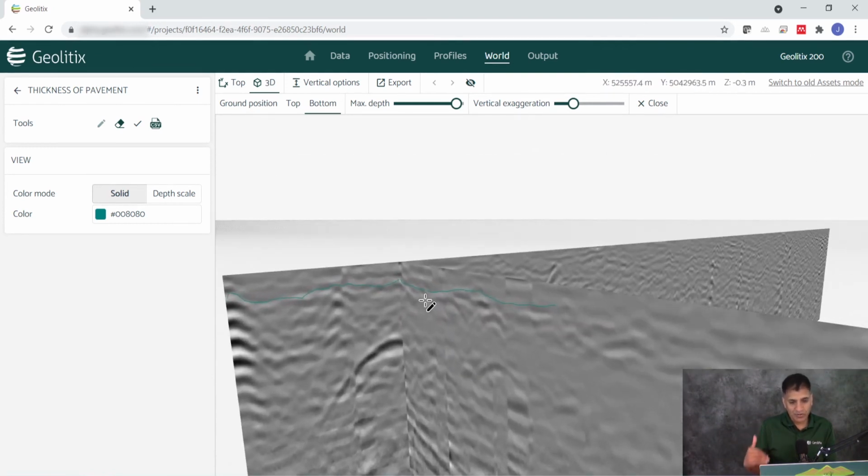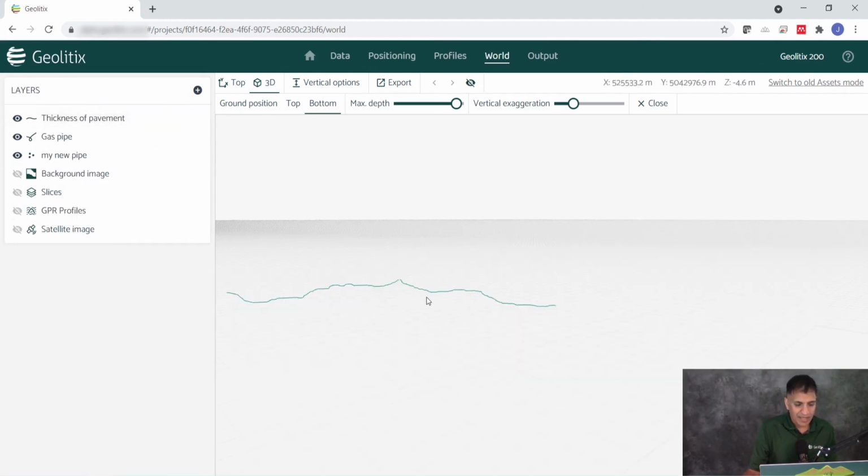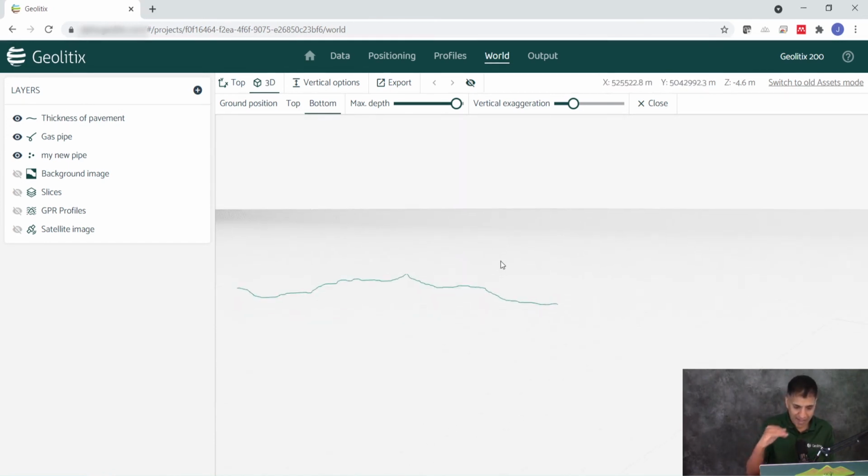But why is that important? Because when you're doing a geological horizon mapping exercise, you really want to have those intersects match as closely as possible. So this is an intuitive way. Let's just go back to turn off. Yep. It's an intuitive way of making sure all of your intersects match as closely as possible, so when you go to create a depth grid, which you do within Geolitix as well, you have a nice smooth surface. So that's a pretty neat and very important functionality as well.